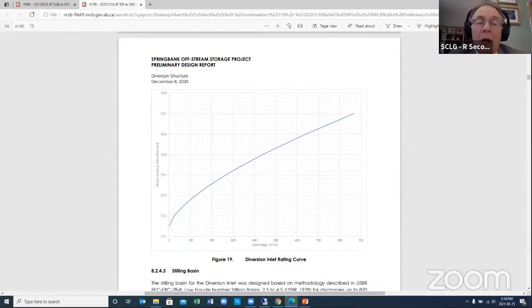But the bridge bottom is at an elevation of 1215.5. So how much freeboard is achieved at the design flow? Well, as I said, the bridge has no effect on the flow during the design flow. The water's underneath it. And as the figure I referenced shows, and the physical modeling demonstrates, the water doesn't hit the structure and it doesn't affect it.